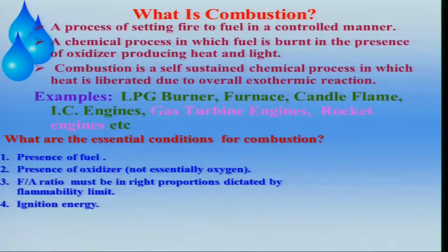That means, to summarize, fuel and oxidizer must be there, and the oxidizer need not be only oxygen, right. The oxidizer can be any other thing, and the fuel-air ratio must be in the right proportion, dictated by the flammability limit. What do you mean by this flammability limit? As I go along I will be talking about it, but we will not get into it now. And ignition energy. The question arises, what will be the amount of ignition energy, and all those things we need to look at, right.